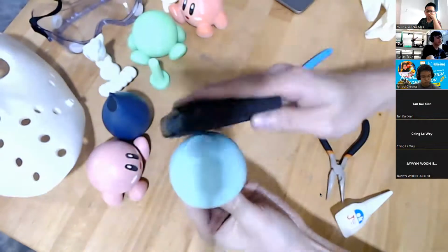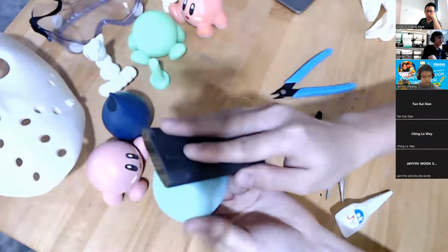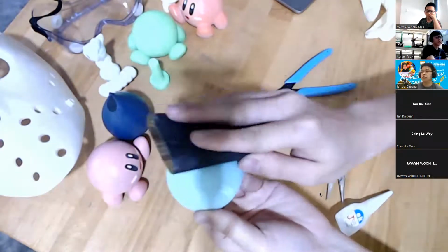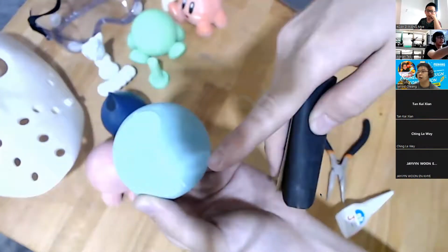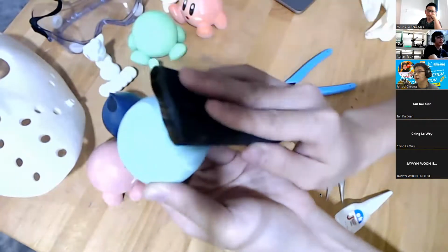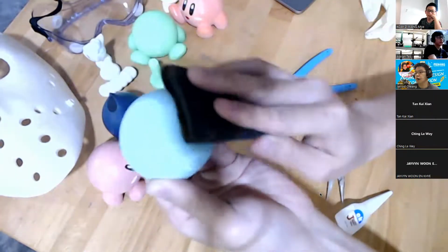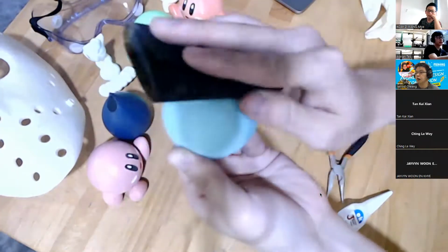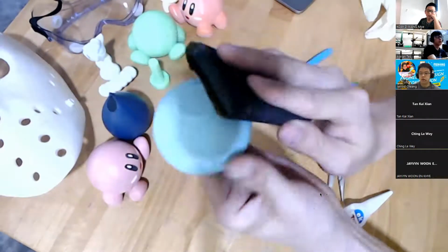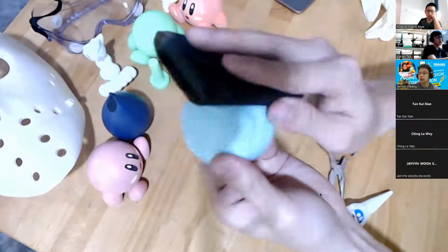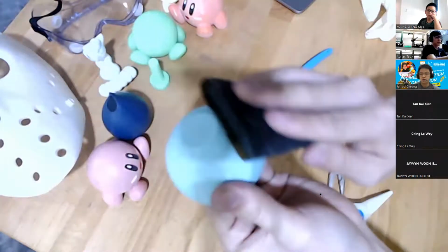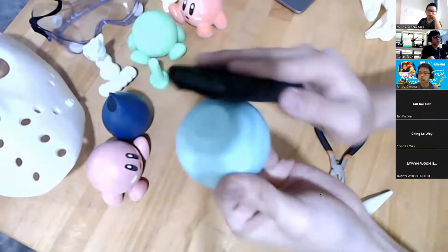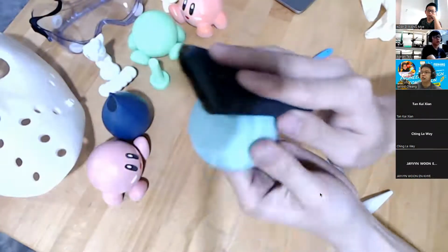This is my part, and then you just sand it up and down. Sand against the line. If the line is this way, go up and down. You want to make sure the line disappears, and then you keep going in circular motion. Move the part. Don't stay on the same place for too long, otherwise the rest will be uneven. So move the part as you go.